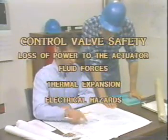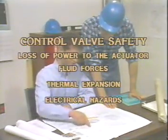Still other important safety considerations are electrical hazards. Electrical devices such as I to P transducers, positioners, and limit switches are often used with control valves. So it's important to know the electrical classification of the area in which the control valve is to be installed, and that any devices on the control valve comply with all pertinent electrical codes. Improper installations can result in explosion hazards.